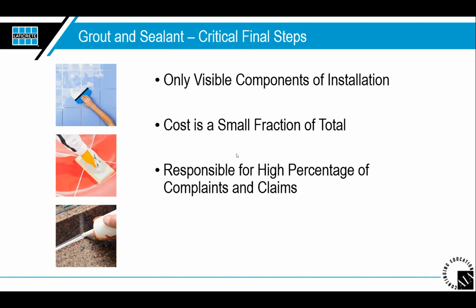So it's funny how sometimes we will actually hear complaints in the industry saying, wow, that grout looks horrible, that grout looks bad. But in reality, they may not even realize that underneath the actual installation itself, they have voids. They don't have the proper coverage for an interior dry scenario, which is 80%. What about 95% on an exterior application, right? They require that type of coverage. They prefer 100%, but I think 95% is now the new standard there, just because of how hard 100% is to achieve.